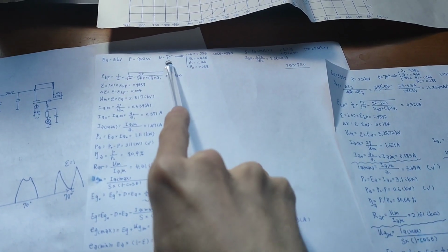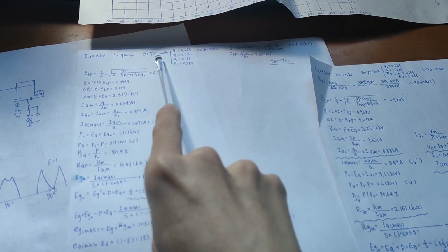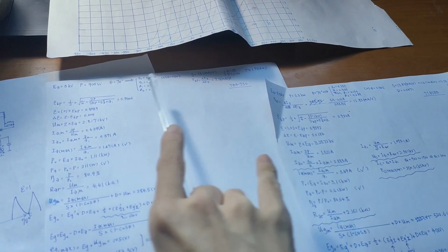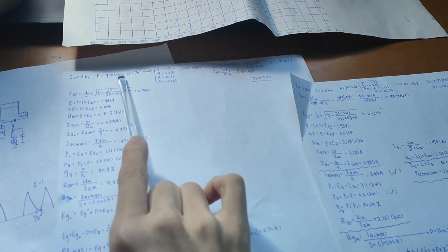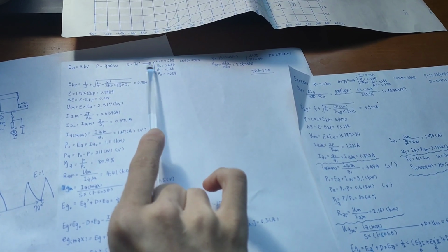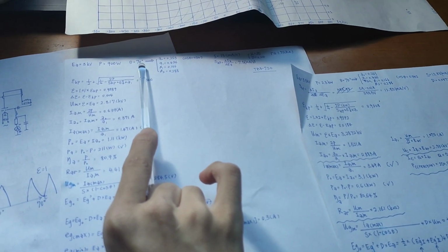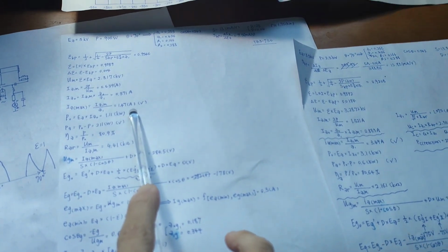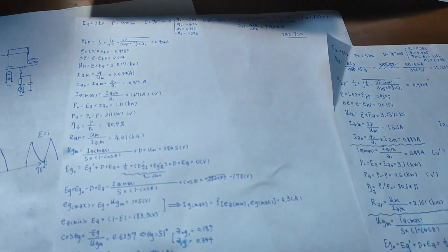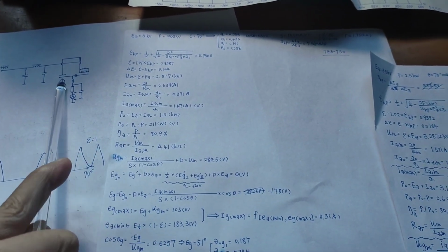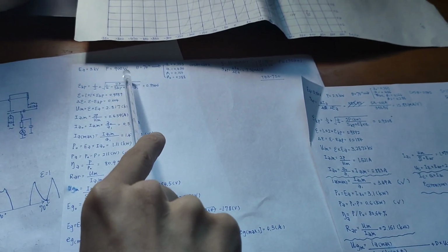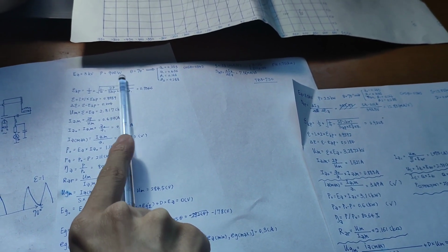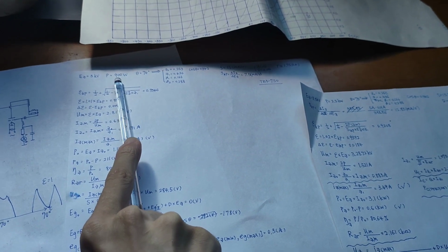And to get a very high efficiency, you will use a conducting angle. I recommend 70 degrees. The first reason is that by using 60 to 80 degrees, you will get high efficiency, and usually your maximum anode current will not go beyond your tube's maximum cathode emission capability. If you just use some very normal power range, do not exceed the datasheet by too much.